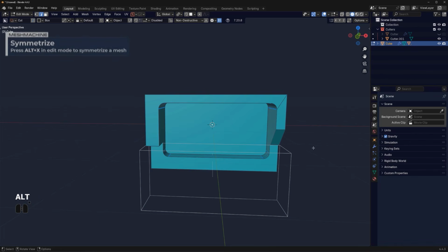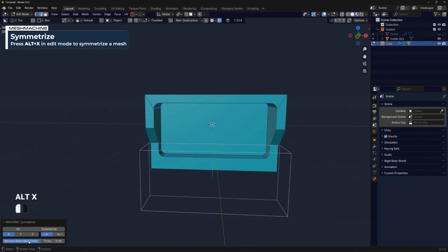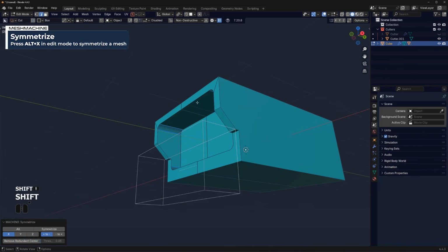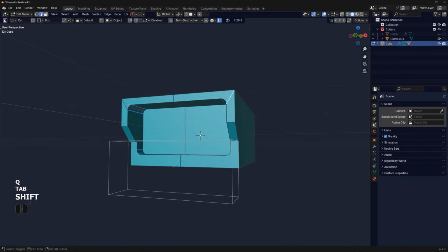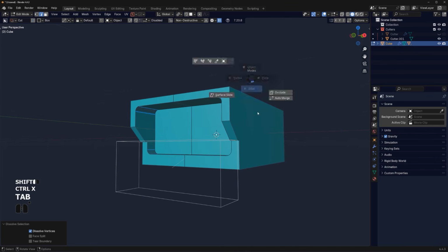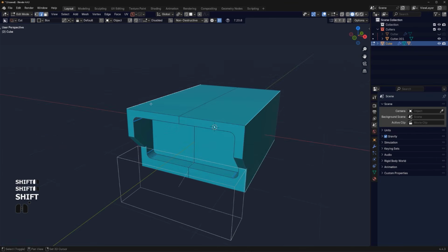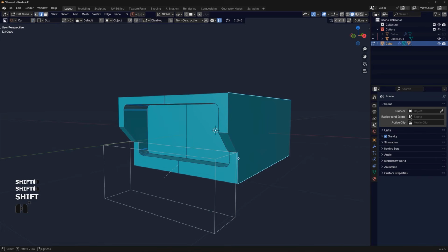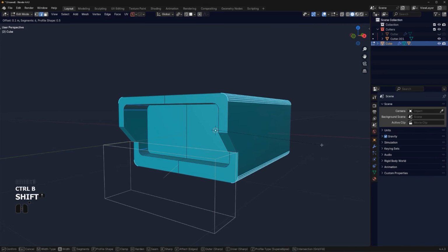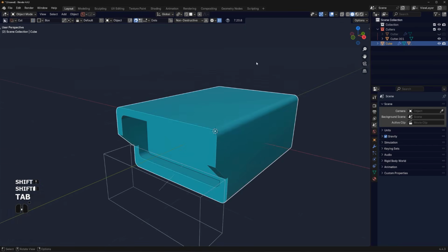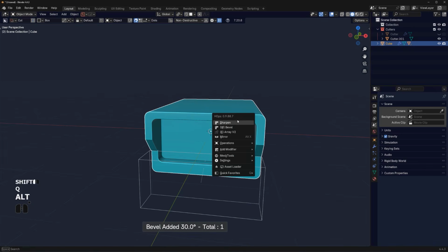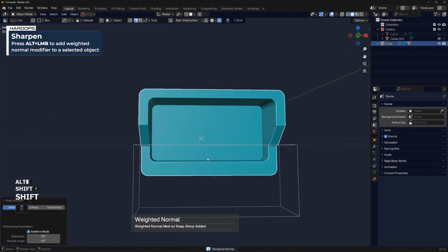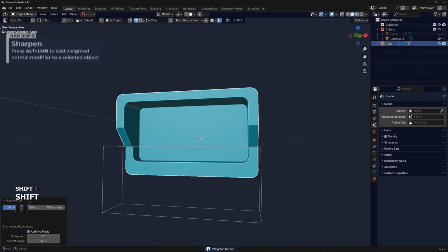Let's just mirror this to the other side like this and run a line in the middle. So we're going to have a nice clean line here in the middle, so we can get rid of these two, which are going to cause problems. And then we're going to grab all these corners here and bevel them as well with 7 segments. And I think it's going to be enough. Run a bevel on everything, thinner, and weighted normals. And now it's a good time to save because, reasons.